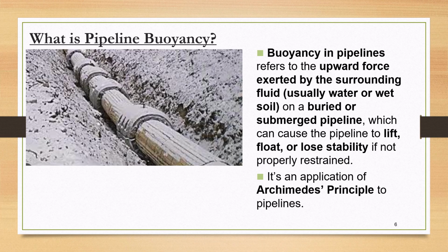So that buoyancy force, if it becomes more than the weight of the pipe, or along with the weight of the soil, it may float and lose stability. It's an application of Archimedes principle to pipelines. So to maintain the integrity of the pipeline system, we should calculate or check if the pipeline will be lifting due to buoyant forces.